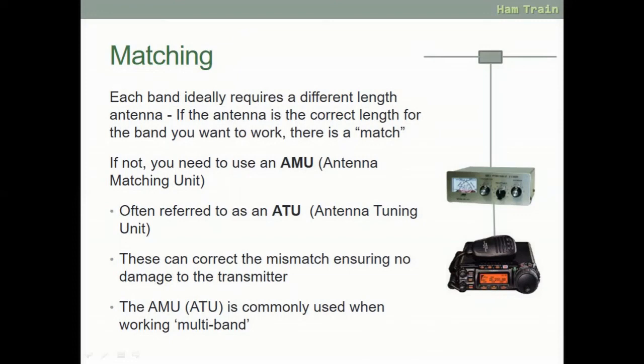And an ATU is commonly used when you're working multiband. So for instance, my antenna, I have one long wire and I use it on nearly every HF amateur band. I could not do that without an antenna matching unit.